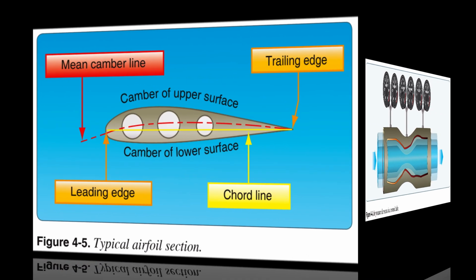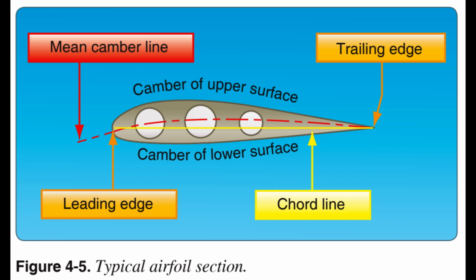Airfoil design. An airfoil is a structure designed to obtain reaction upon its surface from the air through which it moves or that moves past such a structure. Air acts in various ways when submitted to different pressures and velocities, but this discussion is confined to the parts of an aircraft that a pilot is most concerned with in flight, namely, the airfoils designed to produce lift.